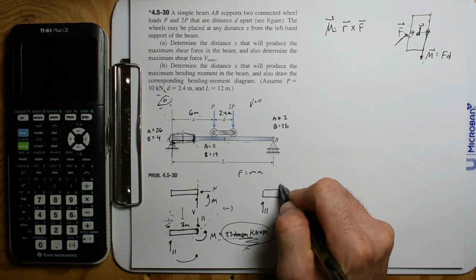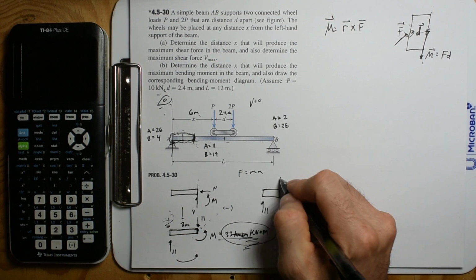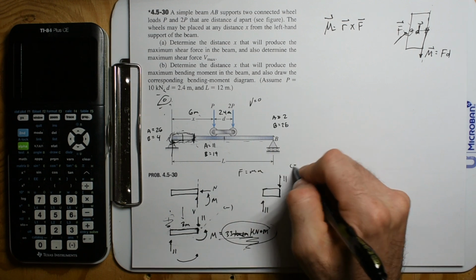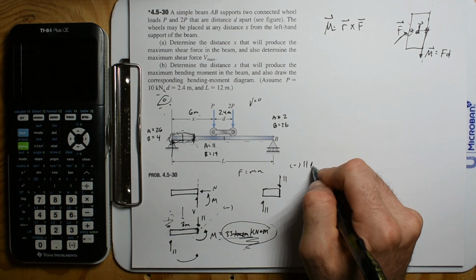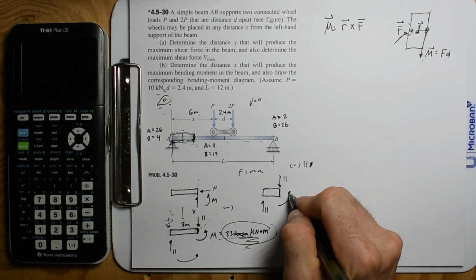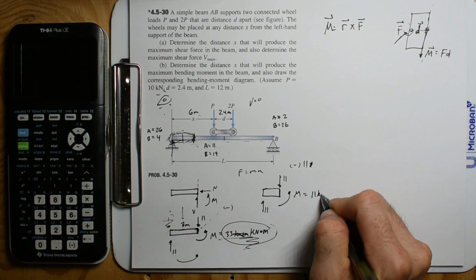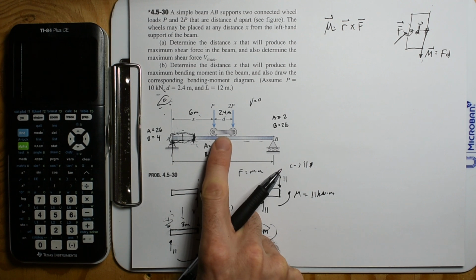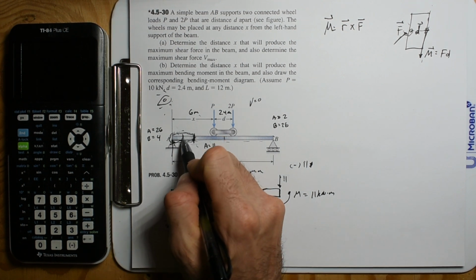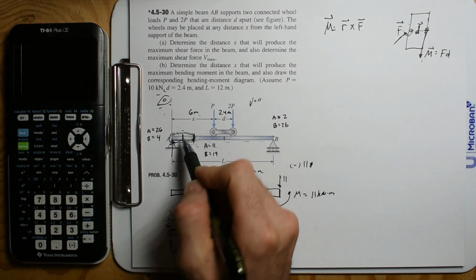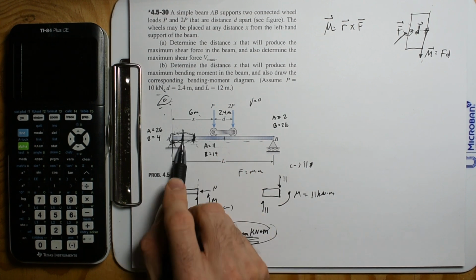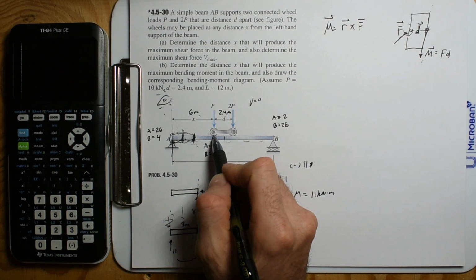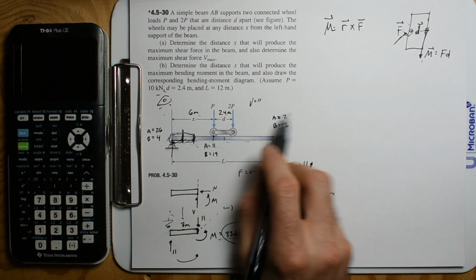We're going to have 11 up. This chunk isn't moving, so we must have 11 down on this cut surface. It looks like we have a negative moment of 11 kilonewton meters, so we have to have a positive moment of 11 kilonewton meters. So now you can see, if we put this thing in the middle, we're going to get less moment at 1 meter. You know what I mean? So maybe we'll get quite a bit of moment out where this thing is out there.